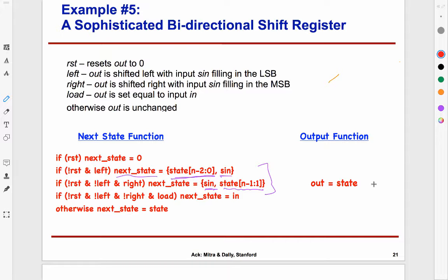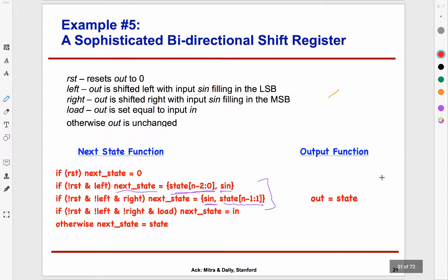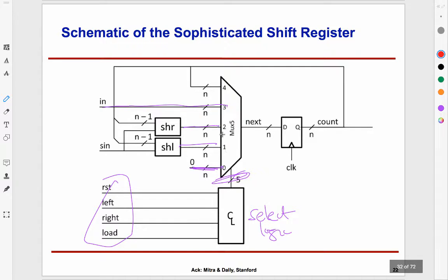And then when it came to implementing it, the style is something that we saw in other examples also, which is we think in terms of the state register, and the multiplexers get to decide what is the next value we are going to feed into that. In this particular case, there were a bunch of choices if you look at the program state. There are 5 possible options, so we have a multiplexer with 5 inputs covering the 5 cases.